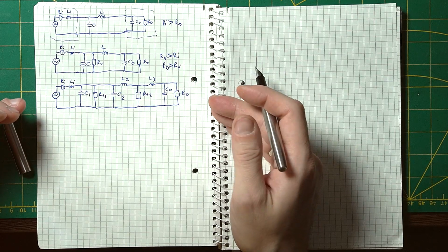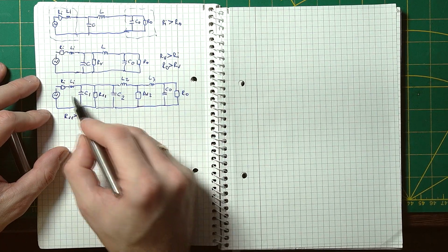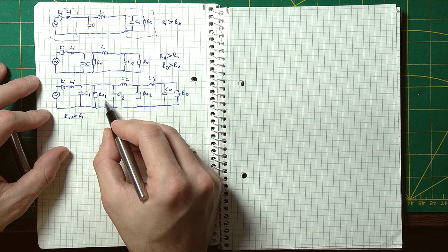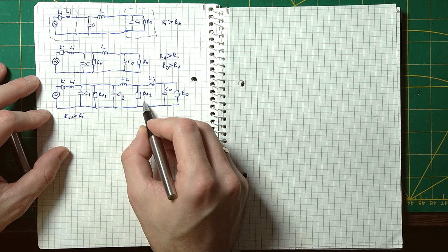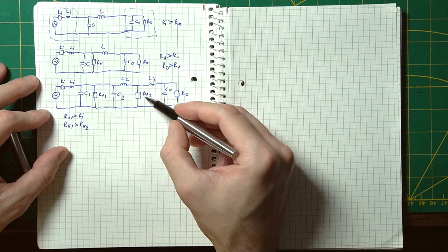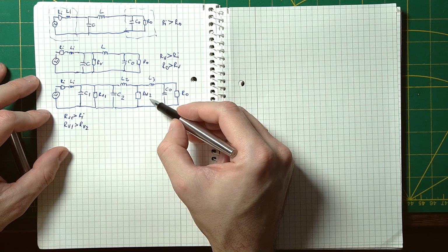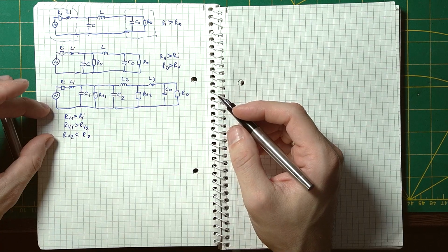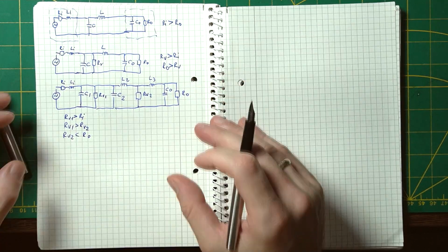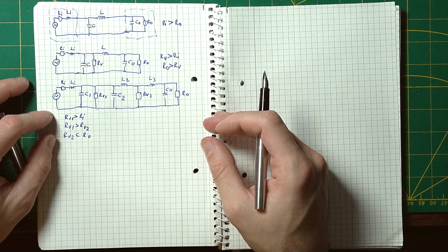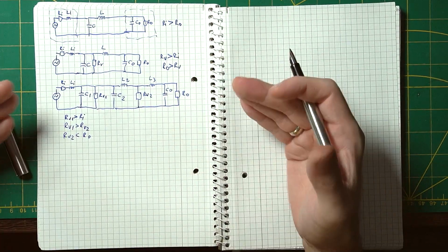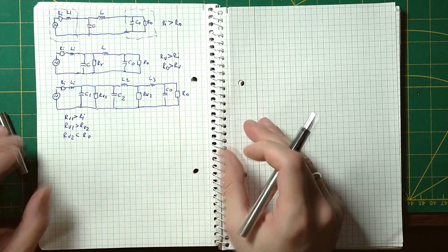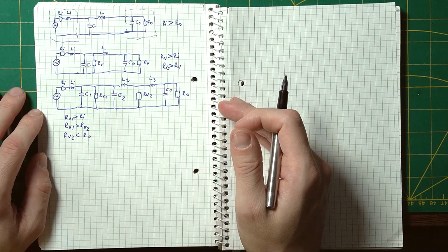To get this to work correctly, we need Rv1 to be larger than our internal resistance, we need Rv1 to also be larger than our second intermediate resistor, and finally we need our second intermediate resistor to be smaller than our output resistor. Now this is something that we can solve. There is a solution in which all of these terms as well as our initial condition are met. So if we can figure out the various components for this network, then we can calculate our final matching network.